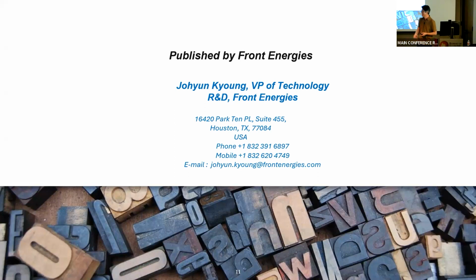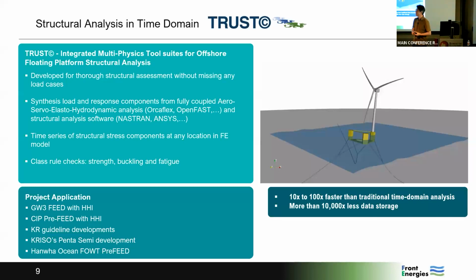Sorry, one question. For the mooring analysis on slide 9, there are branched moorings, where one mooring line branches into two. Is it a spring model or a constraint? The mooring model is our patented mooring model, what we call the Y-shaped mooring line. Close to the hull there is a short line, a chain or wire, and the rest of the line is chain. It looks like it's floating, but no, it's at the seabed. The viewpoint creates a kind of illusion. The end of the chain has the anchor. We can use a pile anchor or a drag anchor; there are many types of anchors. Currently we are using the drag anchor.